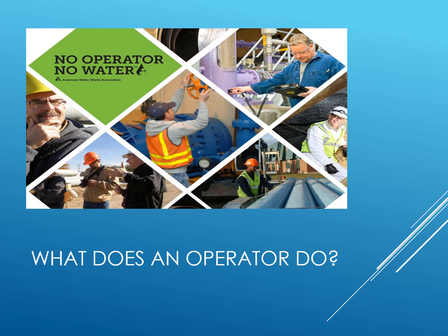They're operating equipment. They operate and maintain equipment used in the water treatment process, including pumps, filters, and other machinery. They also handle chemicals. Operators add chemicals such as chlorine and ammonia to disinfect water and remove contaminants. They're also responsible for sample collection and testing, where they collect and test water samples to monitor water quality and ensure compliance with regulations. There's also the administrative side, record keeping, where operators maintain records of water treatment activities, including chemical dosages, equipment maintenance, and test results.